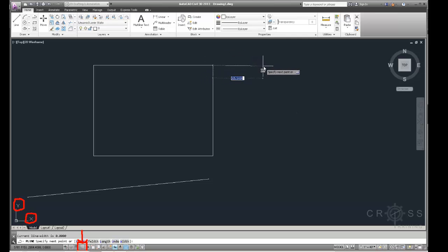So if you zoom all the way in, it looks something like this. I mean, if it's zoomed all the way out, you really can't tell. But when the contractor goes to build this, they can't, because the dimensions don't match up. So to avoid this kind of problem, all you have to do is turn on Ortho. And then turn on your snaps, of course, so you can snap to this corner, and it will go true east and west.